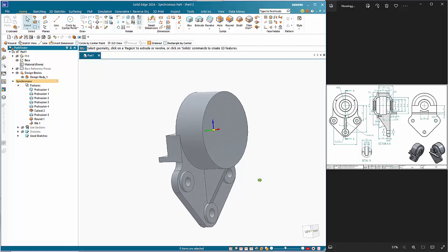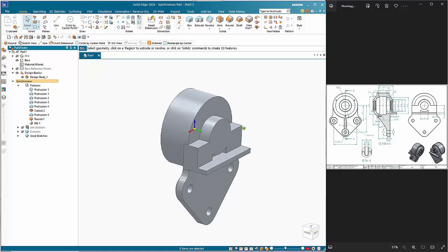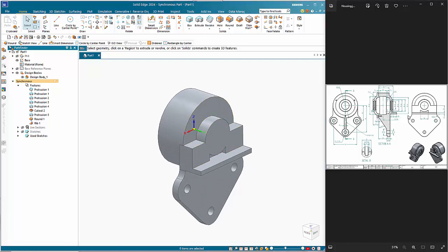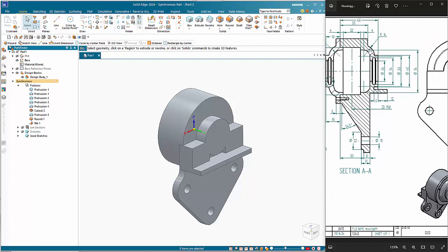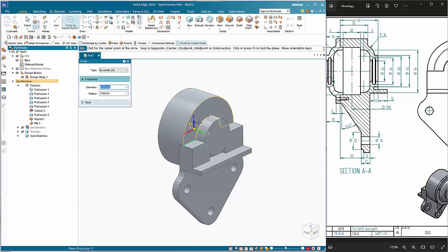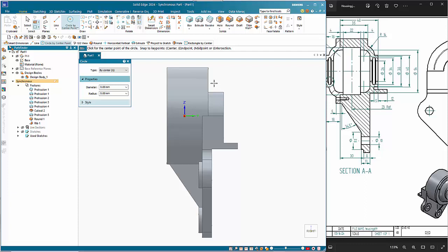So from the rib, let's go back to this rear side. We've got the curve on here. So this is 14 radius on a 38 centers with 11, 15 off of the edge there. So let's create a circle by center. Right mouse click to get the quick pick. Click on the plane there, Control H. So the diameter on this is 28.